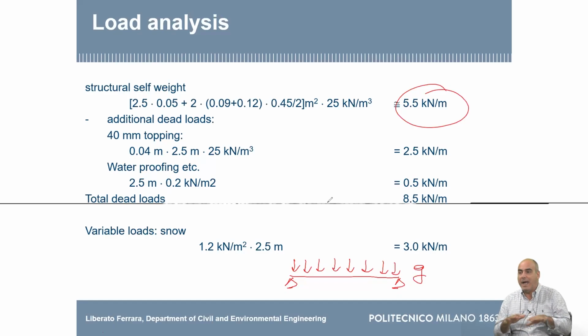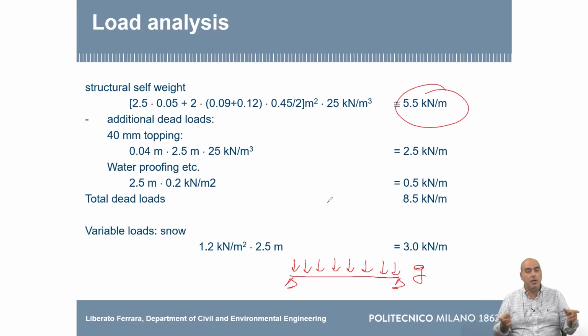But if your roof cannot be normally used, you have anyway to put on them the maintenance loads. And the maintenance loads come in 2 forms. There is a distributed load, but there is also a point load, because if you are there, for example, with an equipment, this equipment can be very heavy and is a concentrated load.